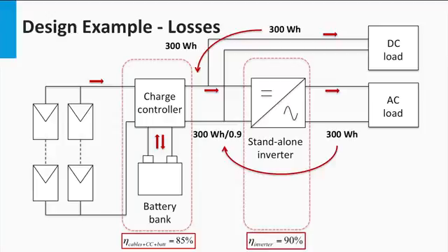Now, these equivalent load energies should be transposed again to the output of the PV array. This is so that we can get the actual amount of PV energy expected by the system per day. Again, we arrive at this total energy need by using the combined efficiency of charge controller, battery and the cables as shown.